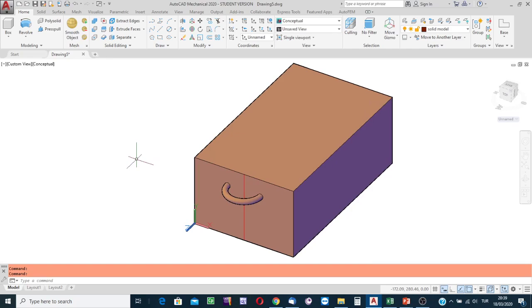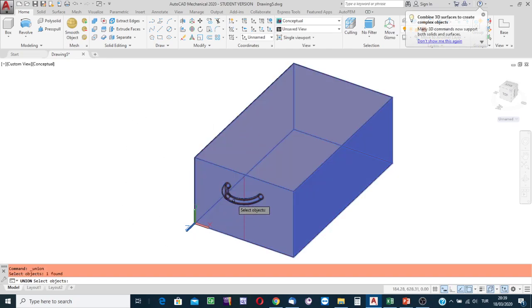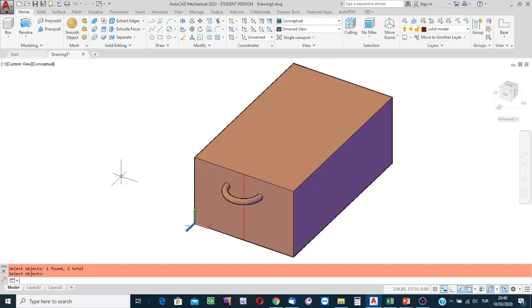So I'm going to apply the addition process. Click on this button, indicate both the rectangular prism and the ring, and then press enter, as they are entities of the same object. Yes, now it is okay. The object right now has two entities, a rectangular prism and such a circular ring.